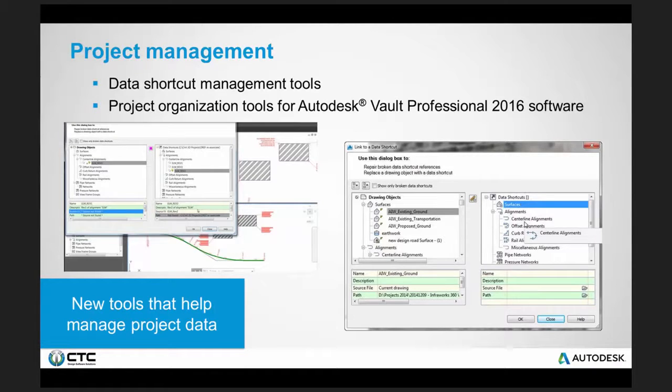There's some enhancements with Autodesk Vault. I'm not sure how many of you guys are using this. It's just a small handful of our clients using it. There's a couple key features there that are really nice. One, I know this was a big catching point for one of our clients. They couldn't fetch Civil 3D data from a different project. So this might be you have two projects adjacent to one another, and you want to just bring in the existing surface from that previous year's project. You couldn't do that. You had to duplicate data.